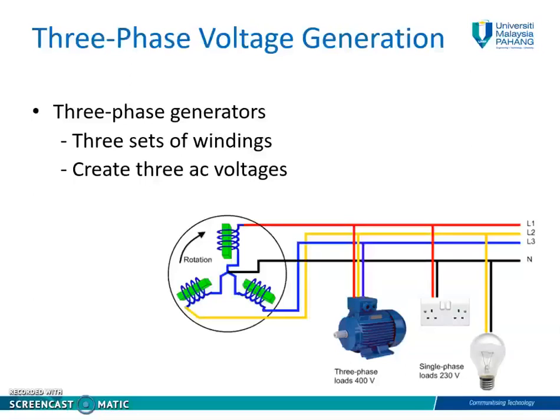Okay, three-phase systems are important for at least three reasons. First, nearly all electric power is generated and distributed in three-phase at the operating frequency of 60 Hz in the US or 50 Hz in some other parts of the world. When one or two-phase inputs are required, they are taken from the three-phase system rather than generated independently.